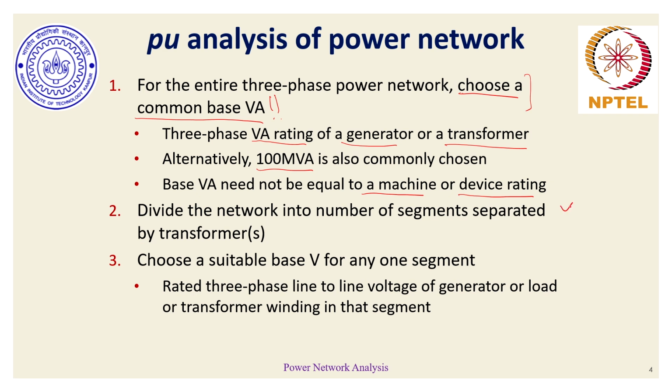By similar configurations, I mean star-star or delta-delta. And by dissimilar configuration, I mean delta-star, which has its own peculiarity. Depending on the types of transformers, the configurations, and the operating voltages, the network can be divided into different segments where each segment might be operating at different rated voltages.